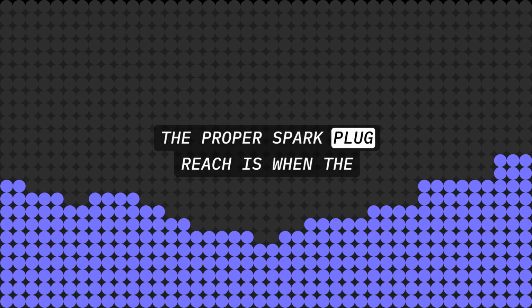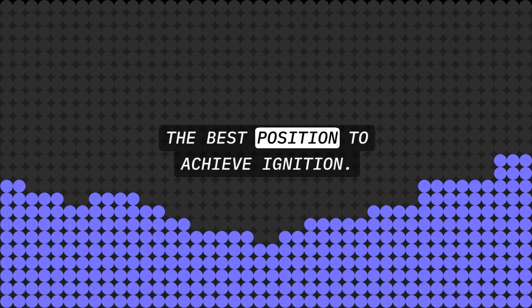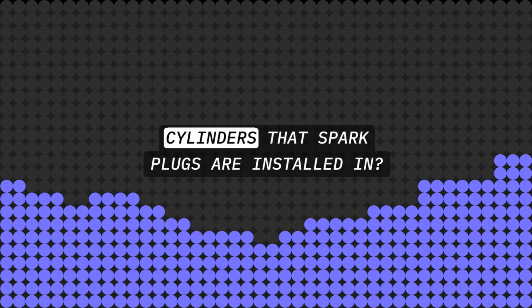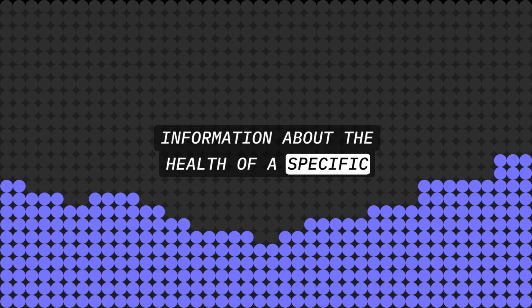The proper spark plug reach is when the electrode end of the plug inside the cylinder is in the best position to achieve ignition. Why is it important to keep track of the cylinders that spark plugs are installed in? Because spark plugs can provide a lot of information about the health of a specific cylinder.